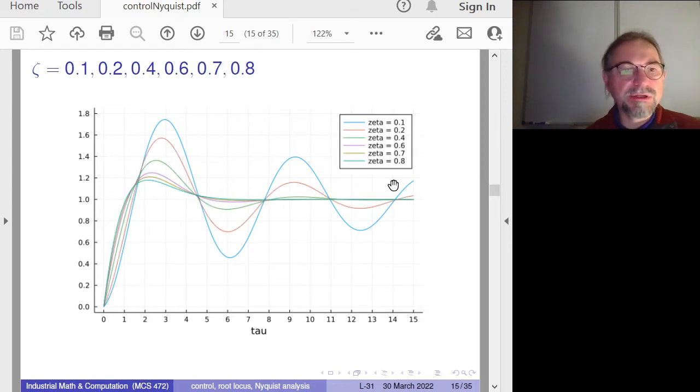So then we will make plots for increasing values of zeta. And you see what happens. So the wobbles are getting less and less in size. So we see already when we go to zeta 0.2, we see a noticeable drop, and it drops again at 0.4. We could keep on doubling. The last value seems to be the best value. We clearly see that we get below the 1.2 mark. So the zeta equals 0.8 will be a very good value.